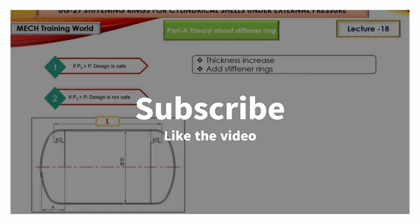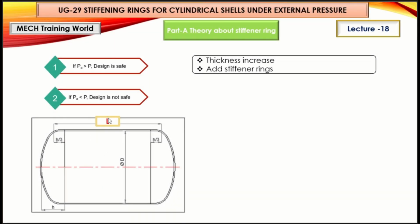So this is our pressure vessel, which has L as the unsupported length. For this, our PA is less than P, so our design is not safe. So we have two optimum solutions. Either we need to increase the thickness throughout the shell, or we need to add stiffener rings. If we increase the thickness, the weight of the vessel increases, the manufacturing time increases, and the cost of the equipment increases. So the preferred option is option B, to add stiffener rings as an adequate solution for the pressure vessel.